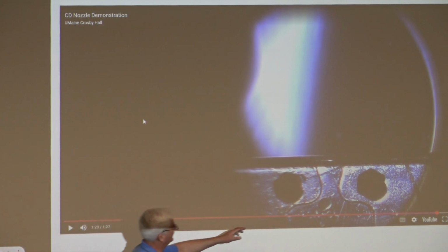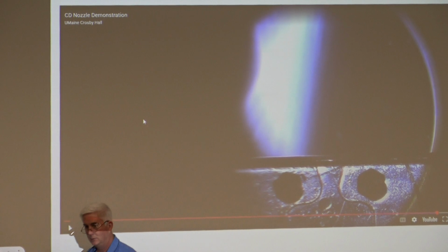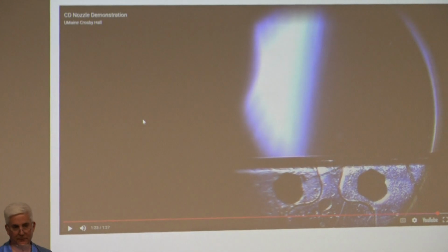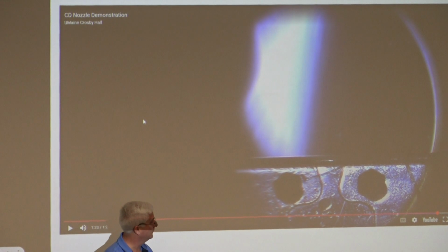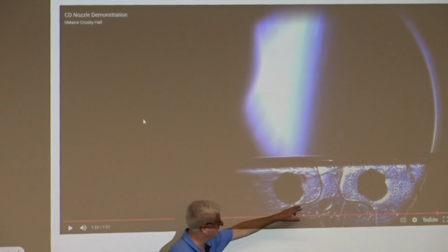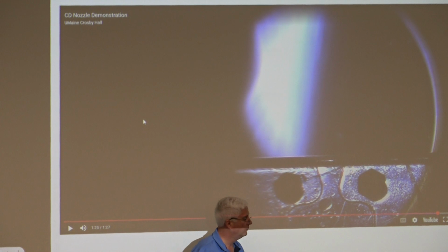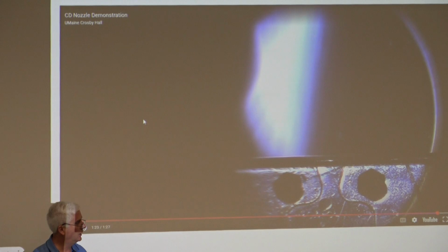So this idea of the converging-diverging nozzle, that's a rocket nozzle. We also put them on the back of high-performance aircraft, like the F-35. It can do that same thing because it can develop enough pressure ratio. So by doing the converging-diverging and sending the flow supersonic, we can get more impulse, more velocity, and that will raise your thrust by about 10% as opposed to just coming out straight.